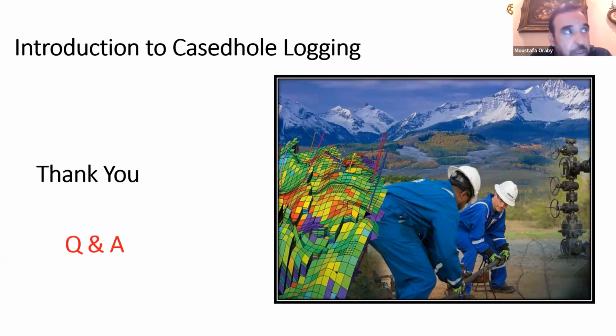Yes. So designing a good cement job, guys. Calculating the proper volume of cement, and you don't just do a very quick calculation, because I saw this in many cases, quite frankly. People do a very quick calculation of cement volume. They assume so many things. They don't rely heavily on the caliper to really calculate the actual cement volume required, and they don't pay much attention to bad cement jobs, and that can lead to a big issue in the future.